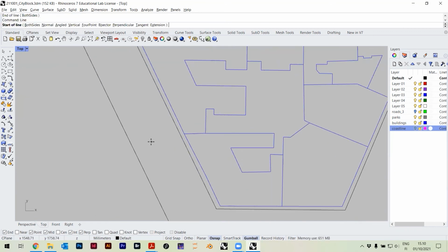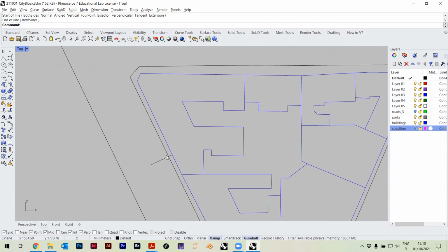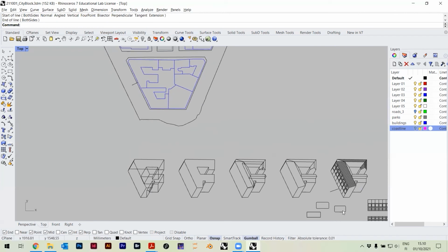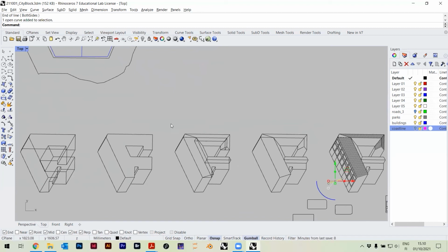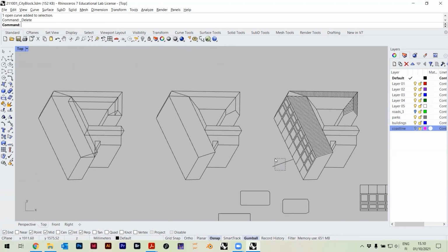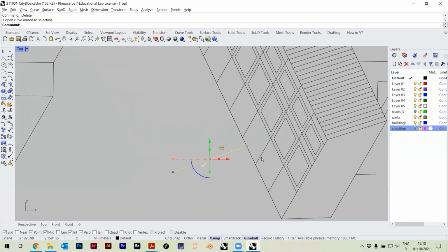So if I have here how my balcony goes, it would be perpendicular to this line. In this case, I didn't rotate the plan, so it's still the same as here. So this is my direction of extrusion. I just have to be careful, and this direction is different than this line here. I just have to be careful how I'm extruding.